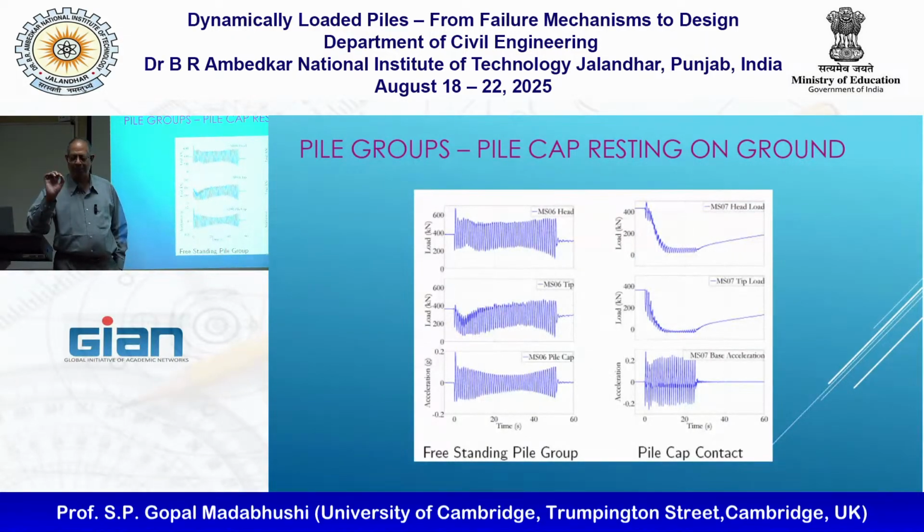It only needs that 0.1 g as a threshold acceleration. After that, it liquefies. You can apply Kobe motions. For liquefaction problems, the input motion shape is not that important. For dynamic problems, it is, but for liquefaction, it isn't, because the soil liquefies and the structure does what it does.